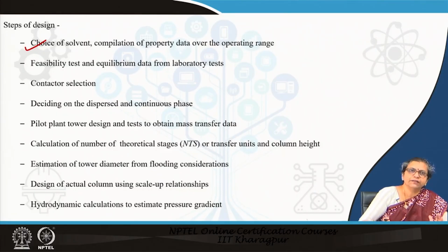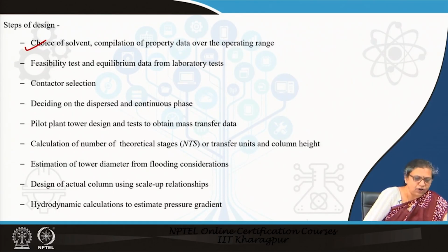Operating range includes the feed composition and the raffinate composition to which you would have to go, and corresponding to that, the concentration of the solute in the fresh solvent, or the solvent which is being used to start with, and the final composition of the extract solution. So, this comprises the entire operating range over which the extractor has to operate for one particular operation. The criteria of selection of solvent has been discussed in the very beginning, in the first lecture on extraction.